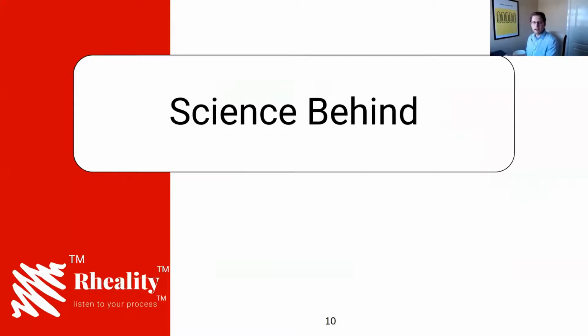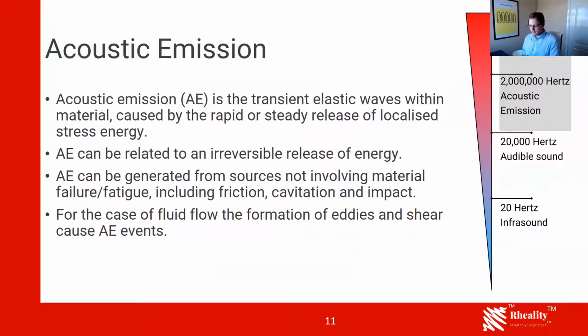So the science behind it: the technology makes use of something called acoustic emission. Maybe some of you might have heard of or even applied acoustic emission to some extent. Acoustic emissions are transient elastic waves within a material, caused by the rapid or steady release of localized stress energy. So there's a stimulus, and that stimulus leads to the release of such energies. It's an irreversible release of energy, and these acoustic waves will always travel to the surface.